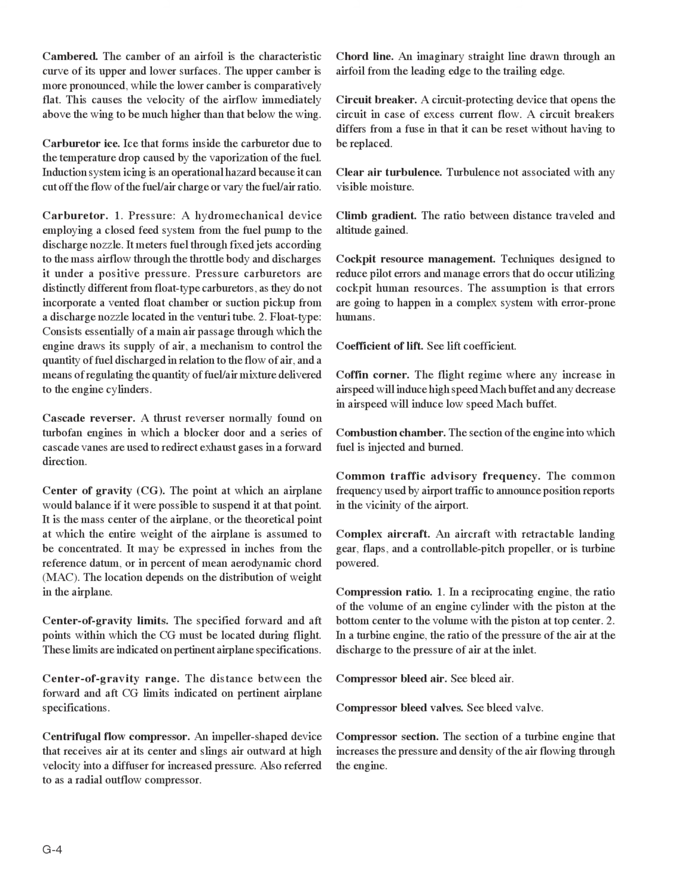Carburetor ice. Ice that forms inside the carburetor due to the temperature drop caused by the vaporization of the fuel. Induction system icing is an operational hazard because it can cut off the flow of the fuel/air charge or vary the fuel/air ratio.